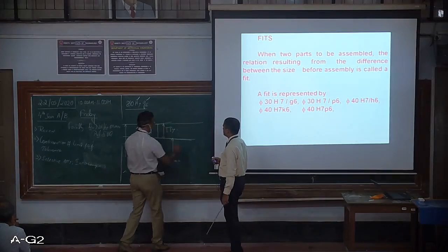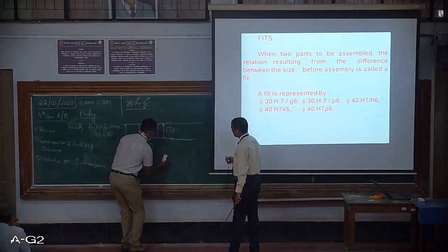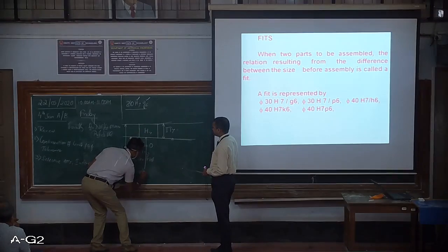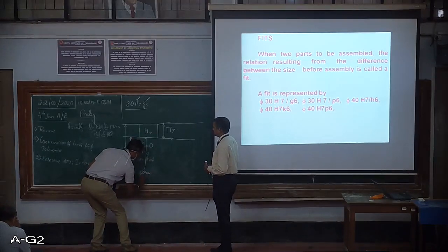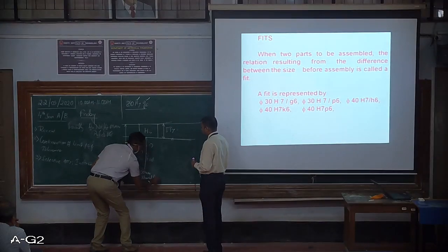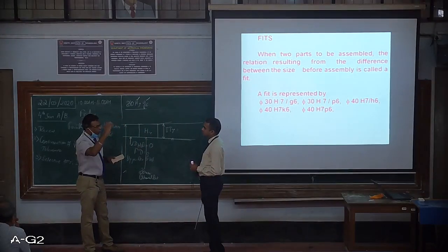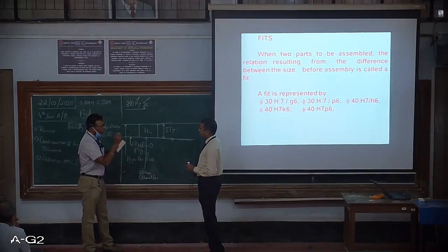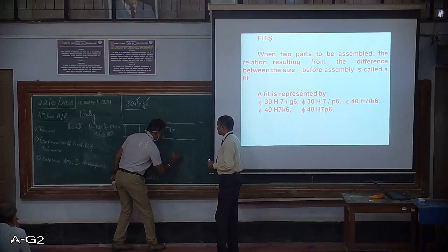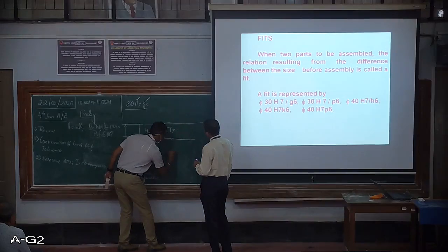Next, let us discuss the G shaft part, G6 shaft. One sec. I will write the nominal size here, 30 mm. So this is the nominal diameter. G6 shaft. G, in the sense A to H shafts are all below the normal line or the XY line or nominal diameter size. So if A is somewhere here, G somewhere here, H is somewhere here, and beyond, this is how the shaft designation goes across.